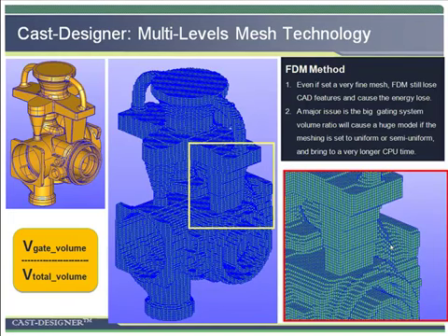There is a major feature of investment casting: the volume ratio of the gate system to the total casting is very high, normally more than 50%. From the simulation point of view, a lot of elements will be wasted if we select a uniform mesh. However, due to the complex casting geometry, it is not easy to set a multi-level mesh size in the FDM or FVM method to save model size.